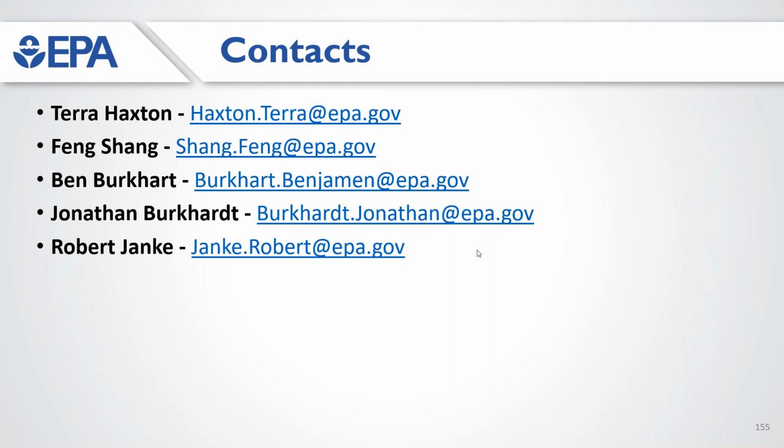Yeah, thanks, Rob. And there's a new question, but it reminded me of an older question, which is related to the tank's residence time. In EPANET, you don't actually explicitly provide that. You provide the dimensions of the tank, and then in the EPS simulation, it will fill and empty, and that's going to give you your residence time. But the new question is, LIFO mixing showed much lower water age. Does that change dramatically if the tank empties?